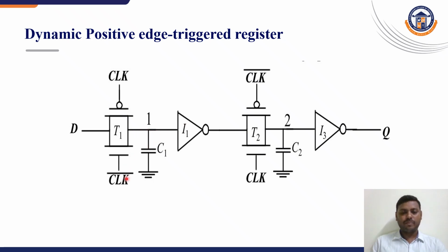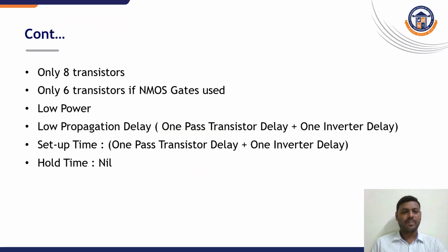When the clock signal crosses the positive edge, the second phase, that is the slave circuit, is switched on and it propagates the master data to the Q stage, that is, the D latch is attained. This is how the positive edge triggered register works.